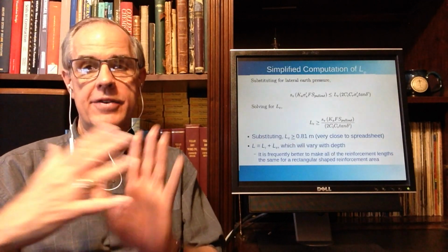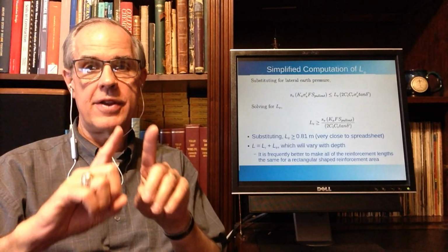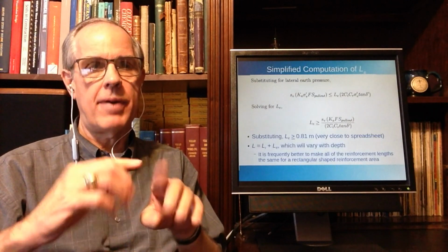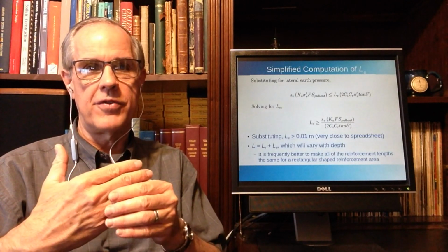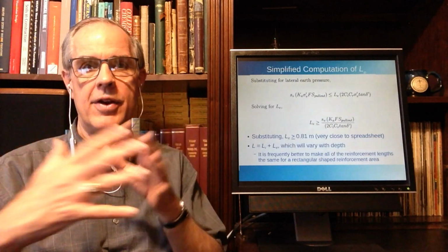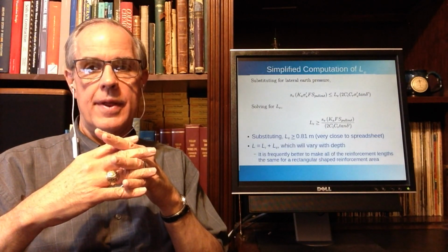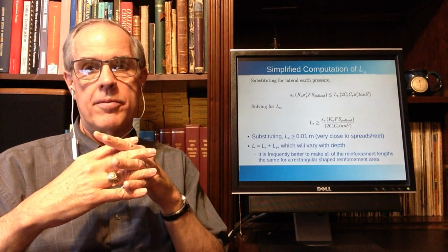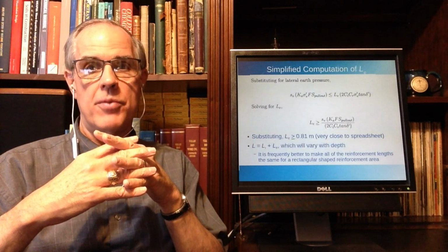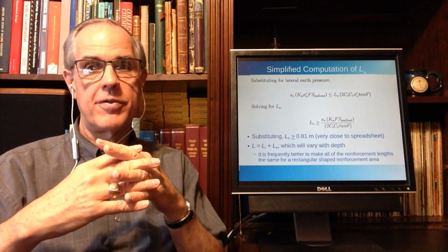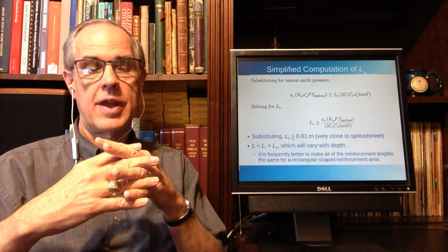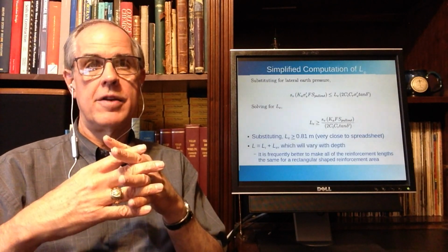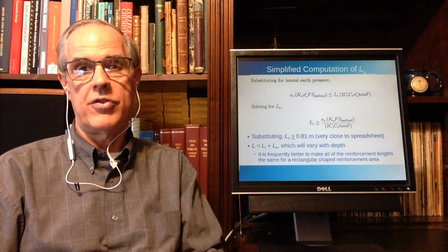That's how you fix it. And this is an interesting case, because in this particular case of MSE wall design, once you get past the technical part of getting the reinforcements to hold everything together, your design is driven more by the requirement to keep overturning from taking place than to keep the geogrid strips from failing, either from pullout or mechanical breakage.